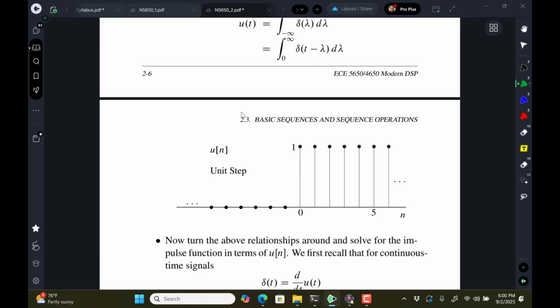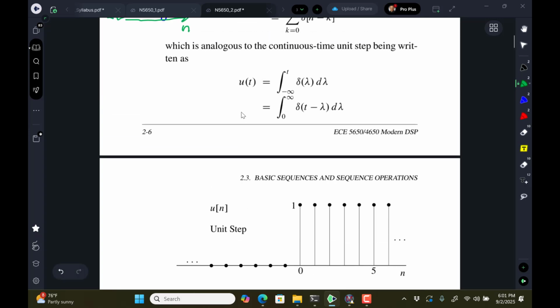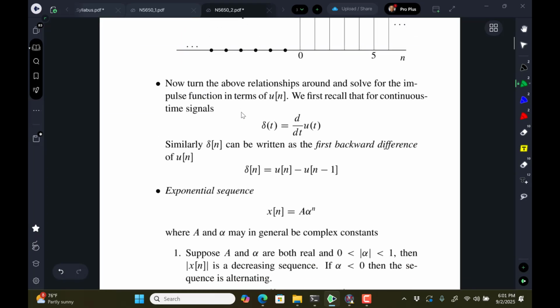You'd say, I can go to the oscilloscope, turn the time-base knob and zoom way in, and what are you going to see? You're going to see that it actually rises up with some rise time, right? Yeah. DSP, not so. It's going to just step like that. So I won't go through these, but you can look at those similarly for the continuous time delta.